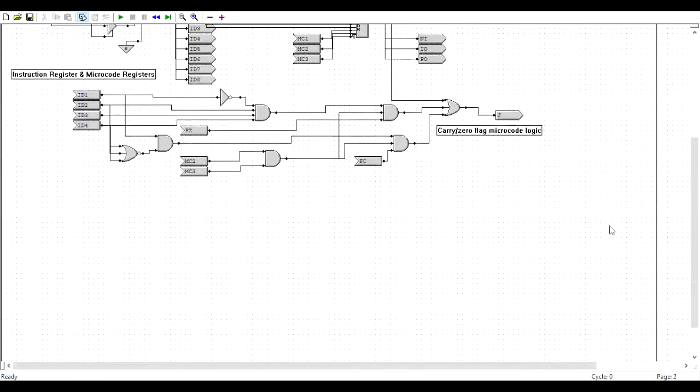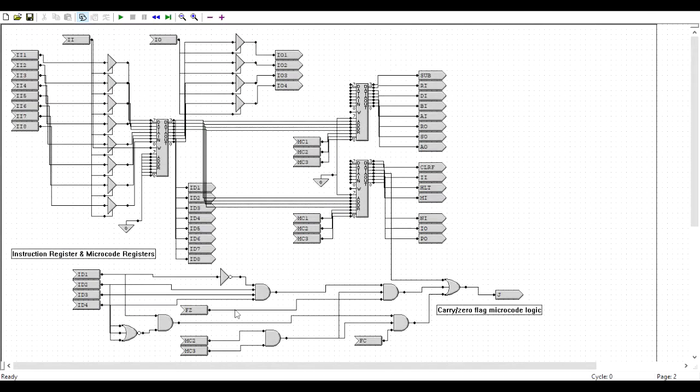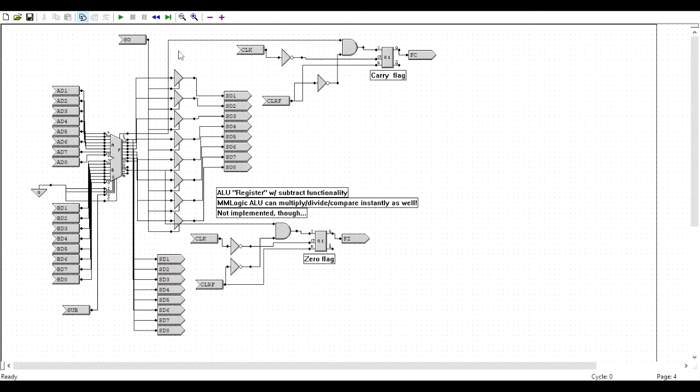But the jump logic is actually determined by a few gates that come out of here and some of the flags. All registers inside this computer are run with these words. So if you want to have some register put something into another register, by bus interaction, it is required that we use these bits right here to control the buffers and to be sure that the buffers are not being overrun by more than one register.